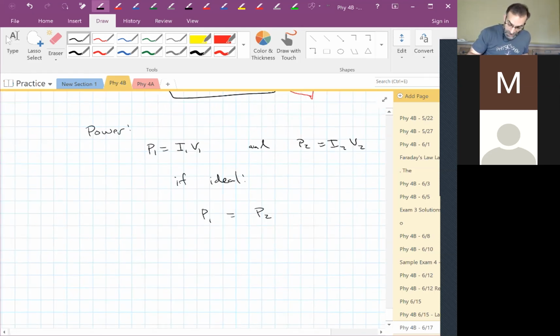So we have I1 V1 equals I2 V2. And what we end up with is I2 is V1 over V2 times I1.